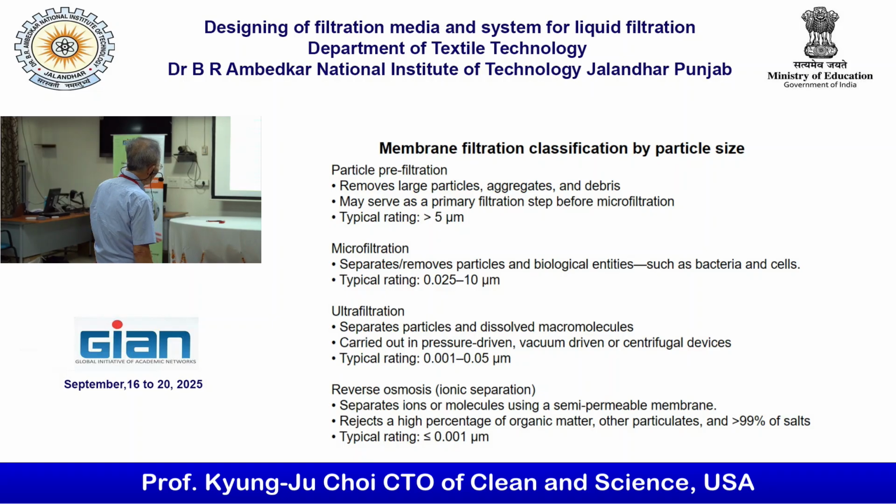Microfiltration removes particles. The typical range is 0.025 to 10 micron. Ultrafiltration is 0.001 to 0.05 micrometer. Reverse osmosis is less than 0.001.